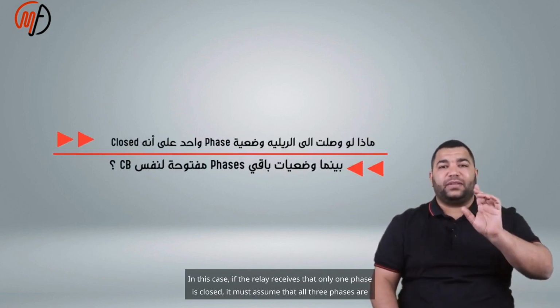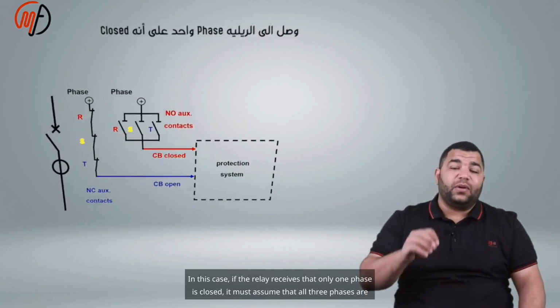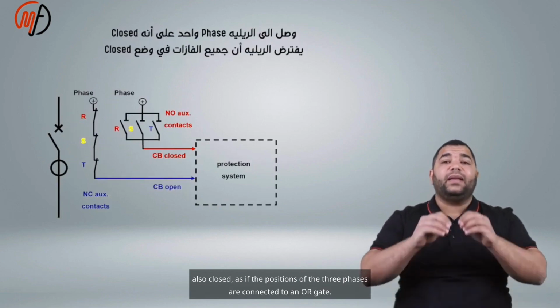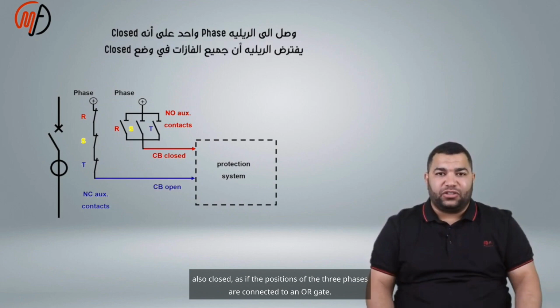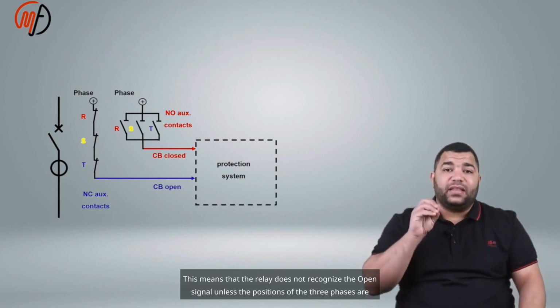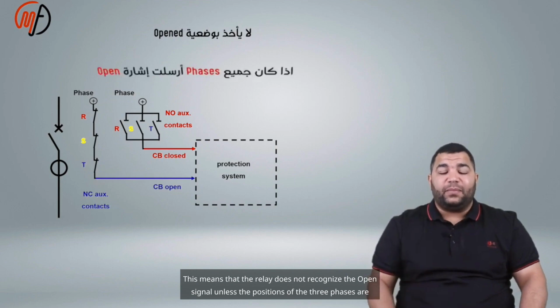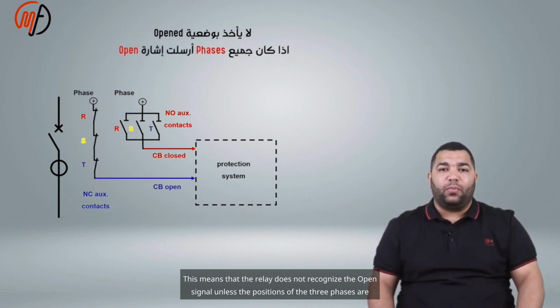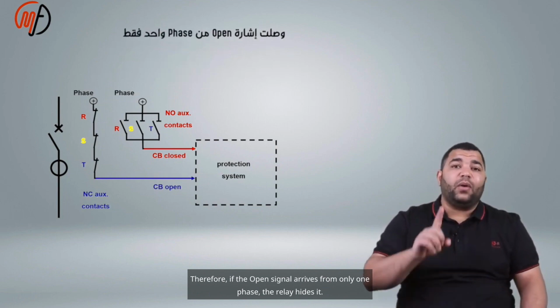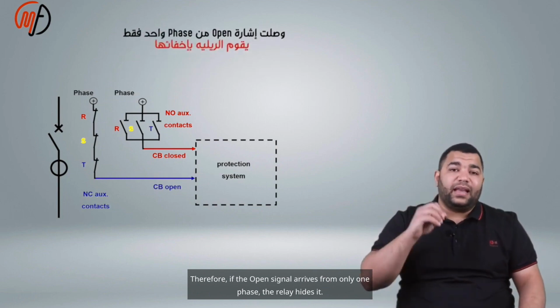Now, what if only one phase is received by the relay as closed while the other phases are open on the same breaker? In this case, if the relay receives that only one phase is closed, it must assume that all three phases are also closed, as if the positions of the three phases are connected to an OR gate. This means that the relay does not recognize the open signal unless the positions of the three phases are open, as if they were mounted on an AND gate. Therefore, if the open signal arrives from only one phase, the relay hides it.